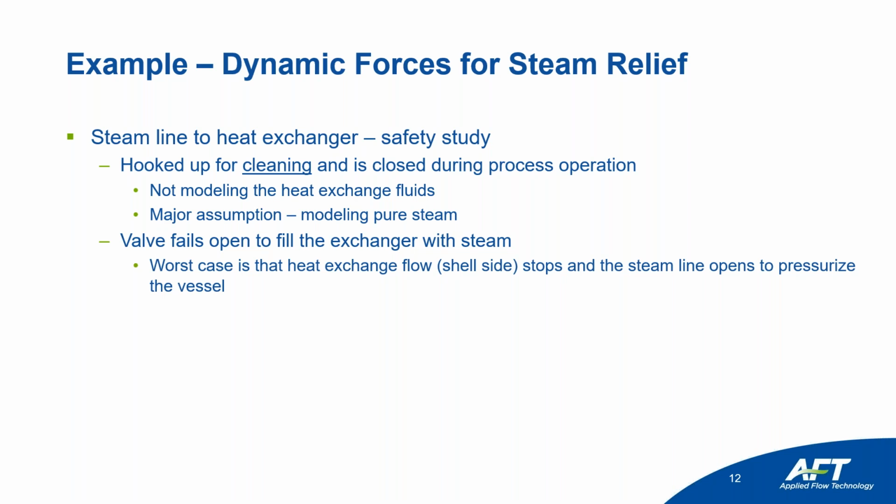The worst case scenario with this, well, you might say, couldn't the steam just exit out with the other flow through the heat exchanger? Well, we're going to assume the worst case scenario is that the flow through the shell side of the heat exchanger stops. So pretty much what this means is we're just charging a tank with steam and then seeing how the relief valve comes off. But it's part of the story.